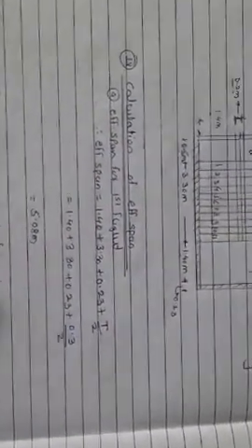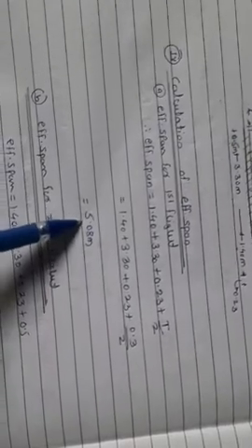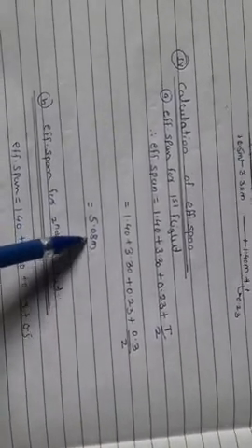So first one will be width of the landing, that is 1.4, plus this total going, that is 3.30, plus width of the walls plus tread divided by 2. So after simplifying this one, we are getting the width for the first flight will be 5.08. Now you have to go for the effective span for the second flight.